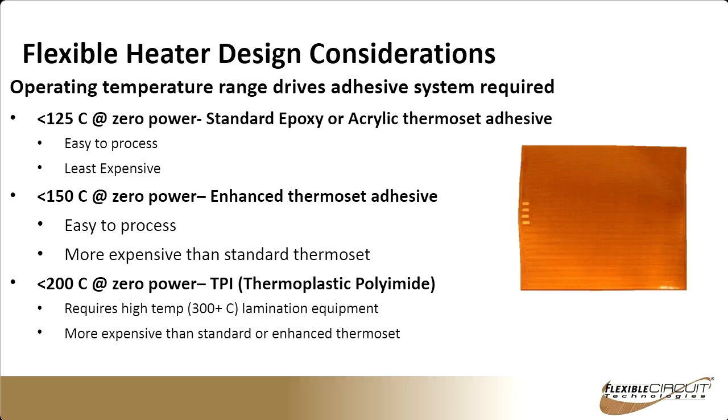And the majority of the heat, I'll be getting into this a little bit more as we go on, but the majority of the heat from a flexible heater is transferred through conduction. There's very little radiated or convection transfer. And so for that reason, virtually all the heaters that we build will have some type of adhesive on it so that they can be bonded to whatever object it is that you're trying to heat, because that's the most efficient way of transferring that heat to the object you want to heat.